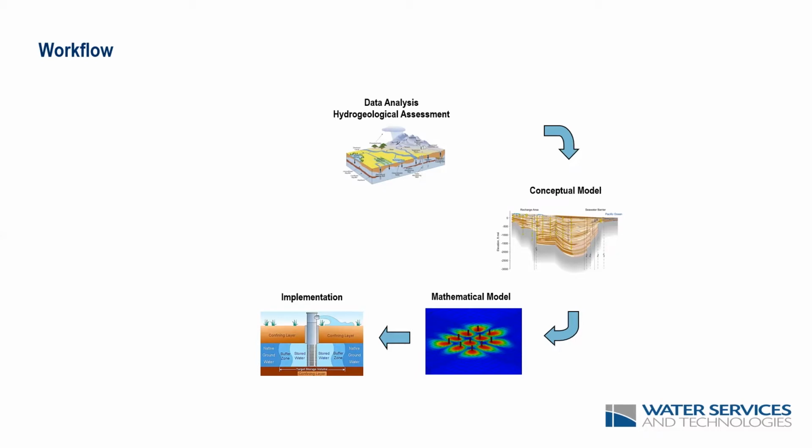So our numerical model will normally be the basis for some sort of system to be implemented on site, especially if we are talking about groundwater abstraction. Any projections we make are always going to involve some level of uncertainty. And then we need to monitor how that system is going to behave, to see if it's going to reproduce what we have projected.